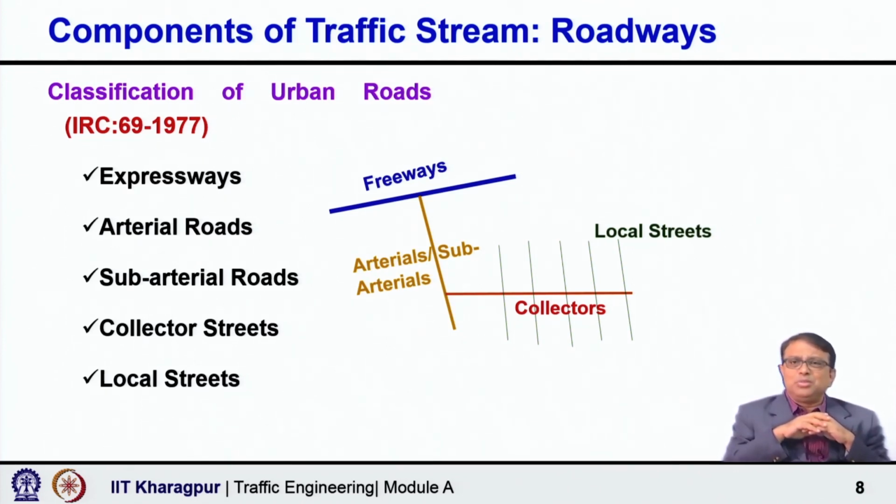A good road does not mean we always need high speed. The function of the road is very important, and here the intended function and the actual function both are important, because maybe the intended function is something, but the actual function is different. So we should care about what the road is actually serving in reality, whether there is any conflict.